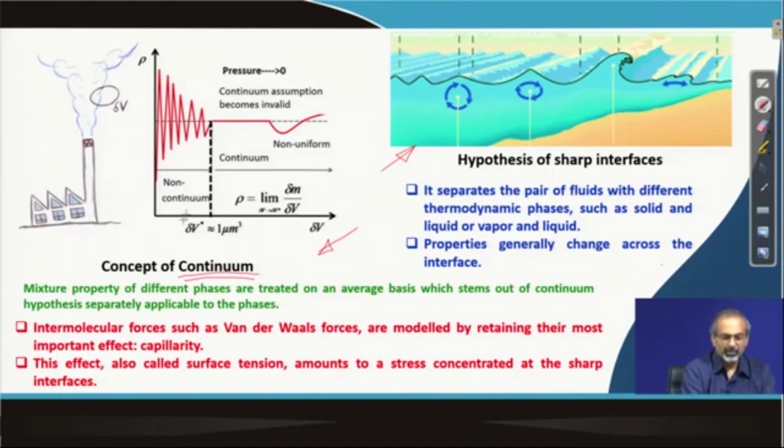If you are operating at atomic scales, then typically you are going to be at a very small control volume, indicated by the delta V region, and then you will find that the properties vary widely and are a function of both space and time, because if you put some kind of a probe into such a small region, then the probe will randomly encounter molecular collisions, and therefore there would be spikes in whatever property it is recording.